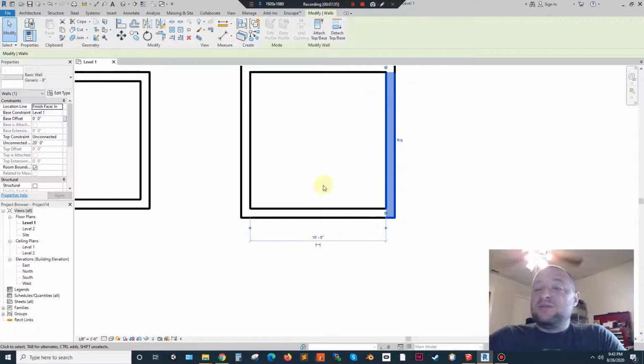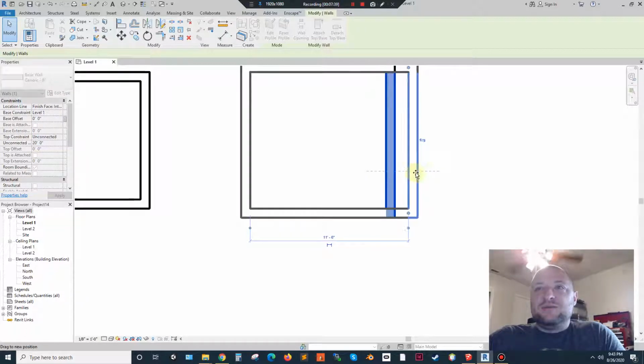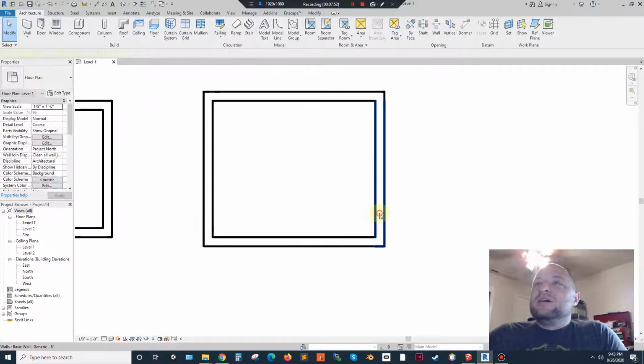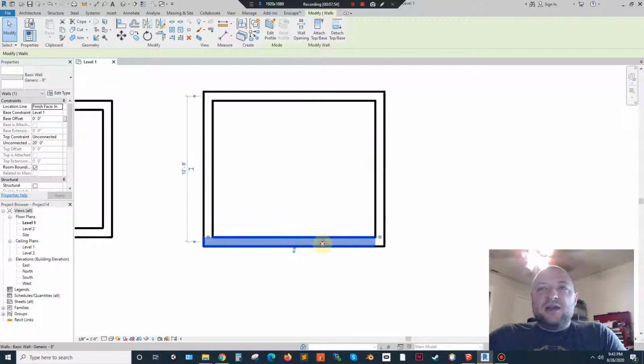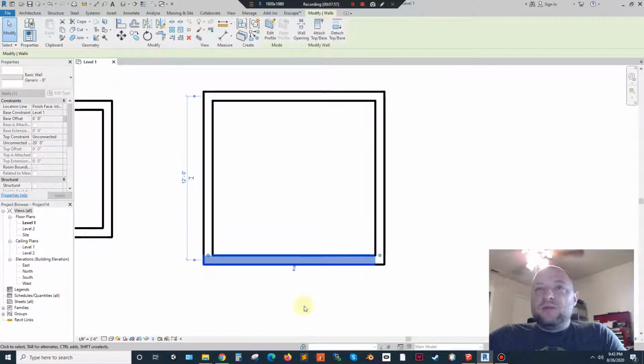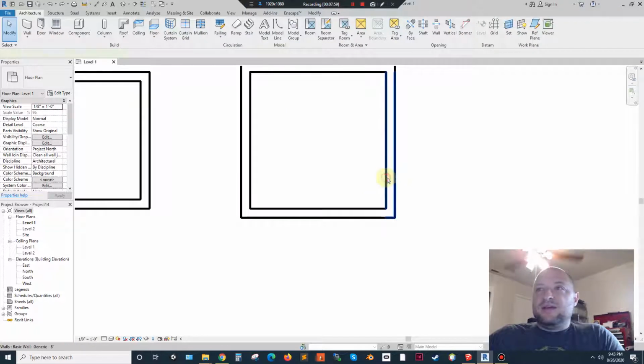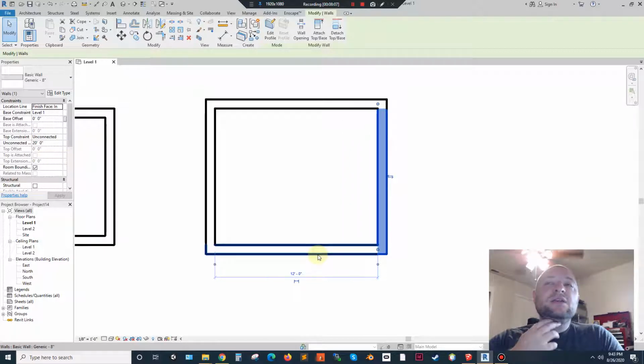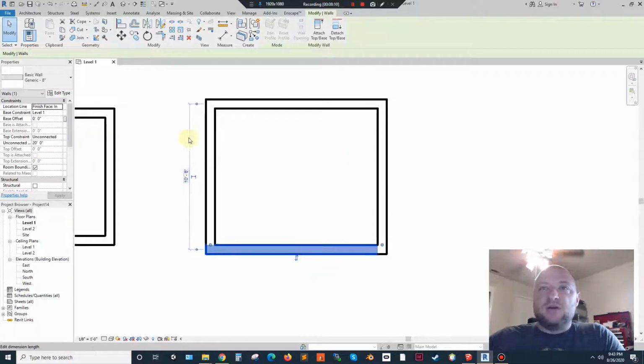Now, let's say that I want to bump this square up to 12 feet. I can click on this and drag this out, and usually you can get it pretty accurately, just like that. Though sometimes you want a little bit better control over it. So let's step back here, and if I click on this, I can actually click in here, and then just like with a lot of other things, I can click on that box and type 12 feet, and it will adjust this out to 12 feet as well.